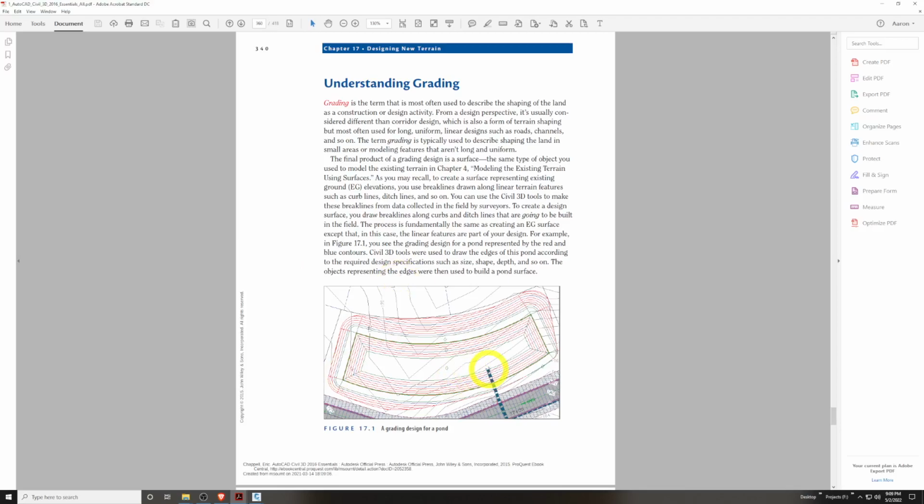But this is a real quick picture to see we're making a pond with certain feature lines and grading objects that has a very uniform shape, but also a unique, very customizable shape that we can bend to whatever we need for this pond to fit in the terrain, or the existing area or location on its site. So this is the contours from the top-down view we're getting used to seeing in Civil 3D.